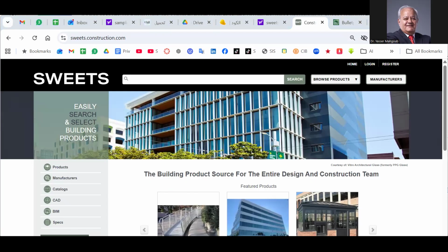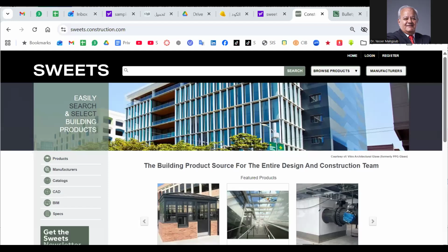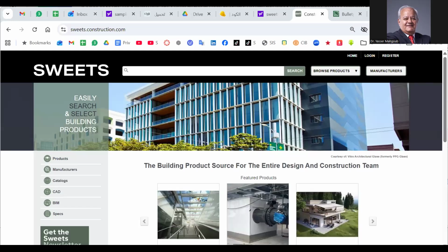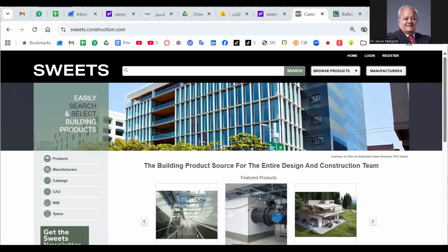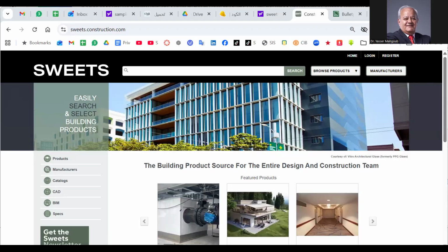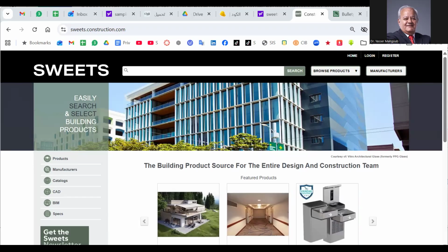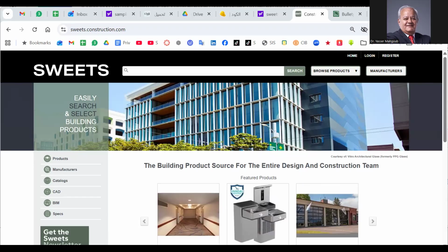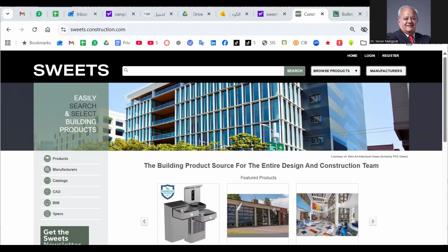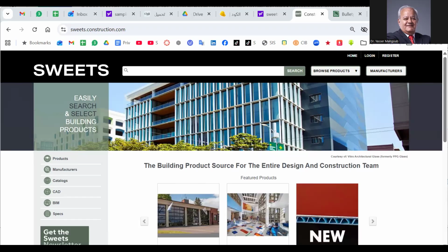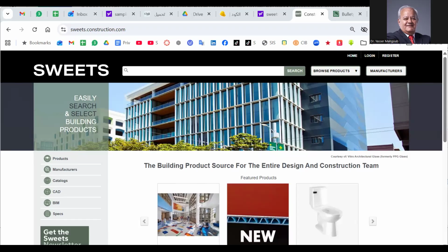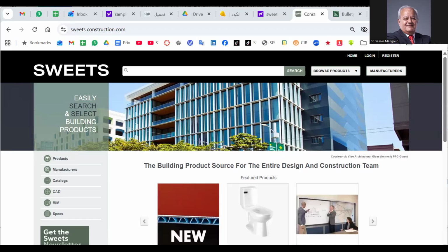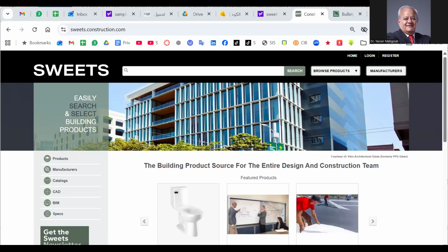Last but not least, you have seen many examples of construction documents, starting from the site, the plans, the sections and details, the elevations. A very important thing is the referencing. So when you want to show a detail, you have to reference this detail according to the drawing number and detail number. Or if there is no detail, the section part of the drawing.